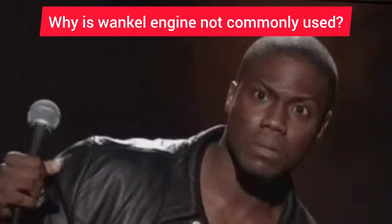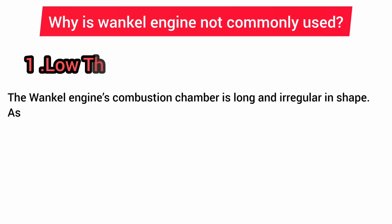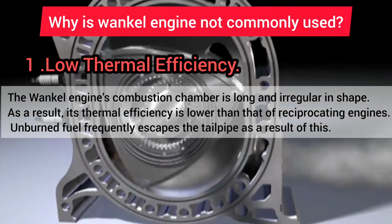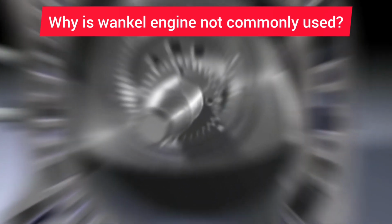Why is the Wankel engine so uncommon? Here are some of the reasons why the Wankel engine is uncommon. 1. Low thermal efficiency. The Wankel engine's combustion chamber is long and irregular in shape. As a result, its thermal efficiency is lower than that of reciprocating engines. Unburned fuel frequently escapes the tailpipe as a result of this.